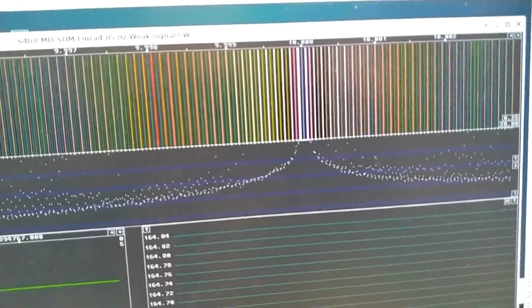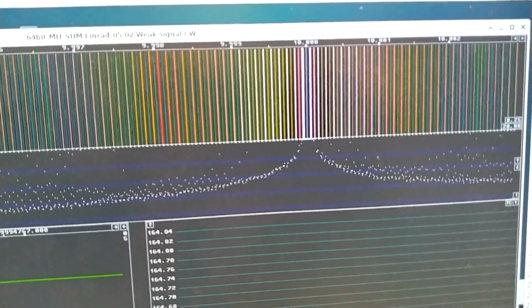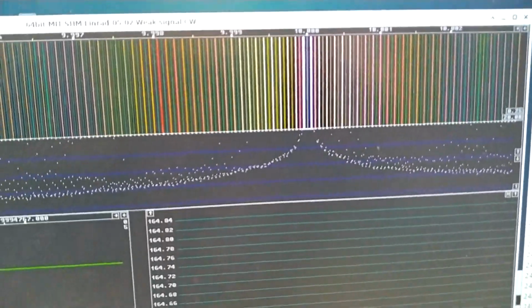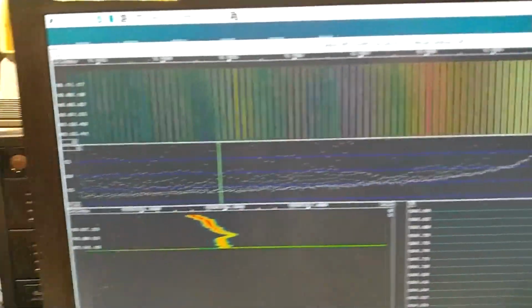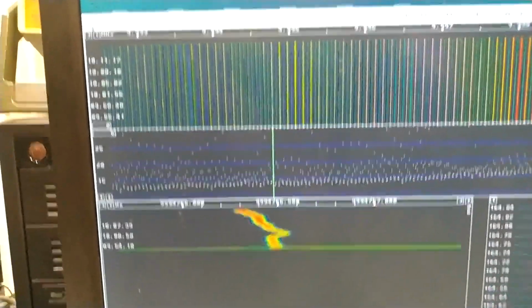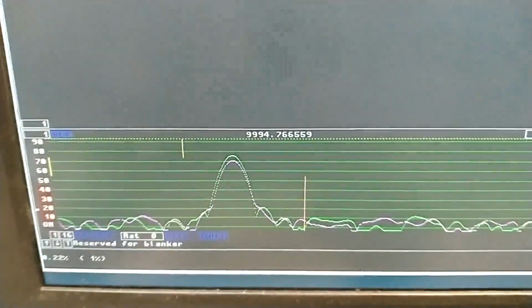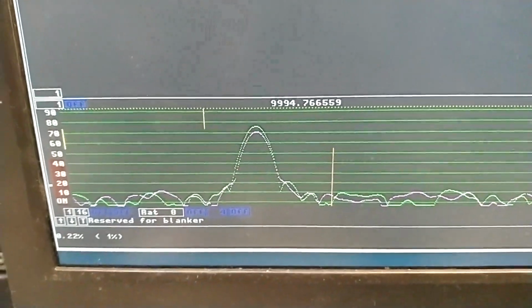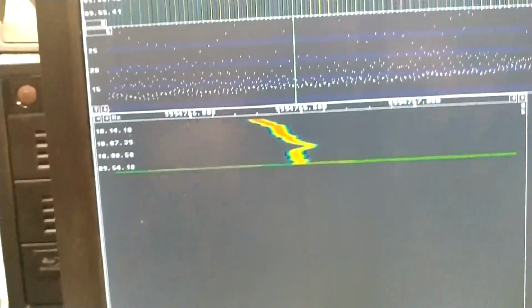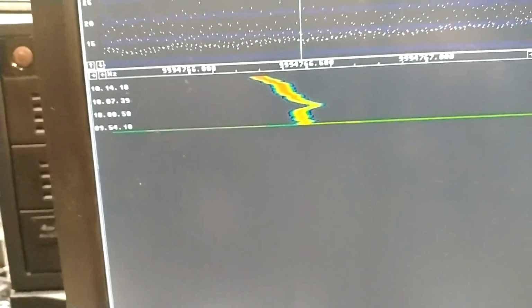I have turned up the signal level to saturate the sound card slightly. That means I get a lot of overtones. And I have selected the 99th, which comes at this frequency, close to where I expected it to be. And here I can see how the frequency drifts.